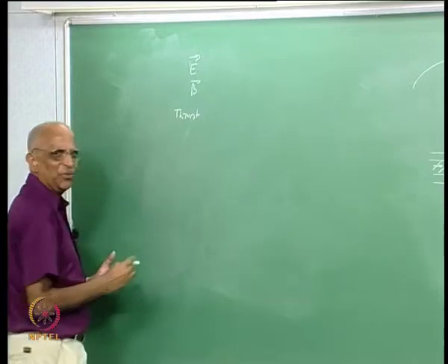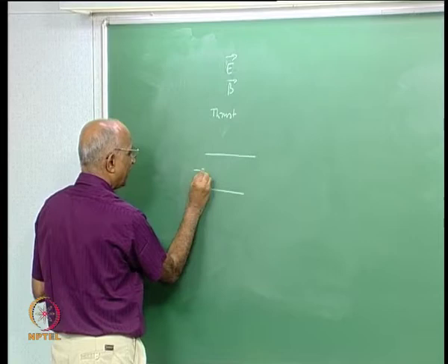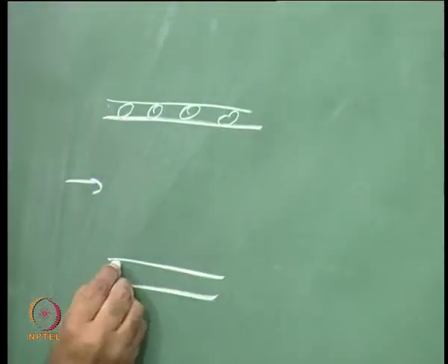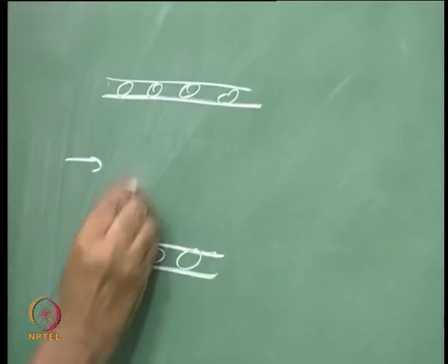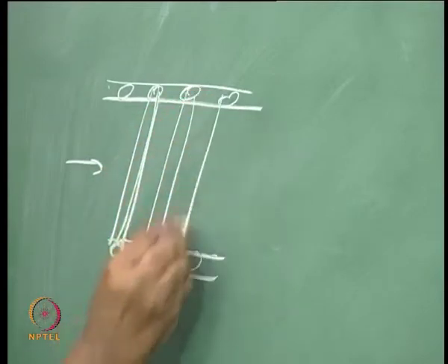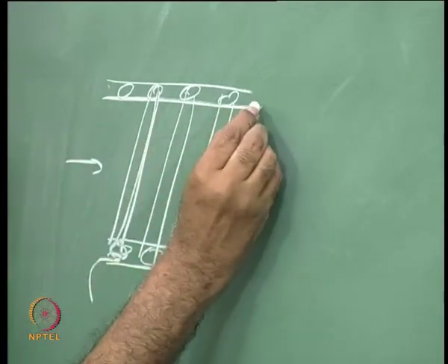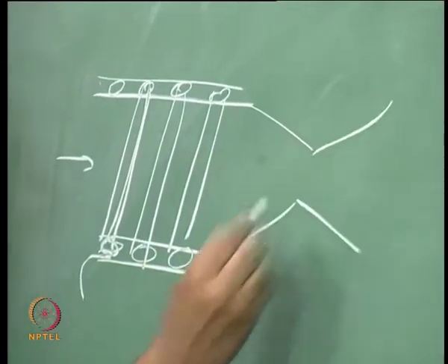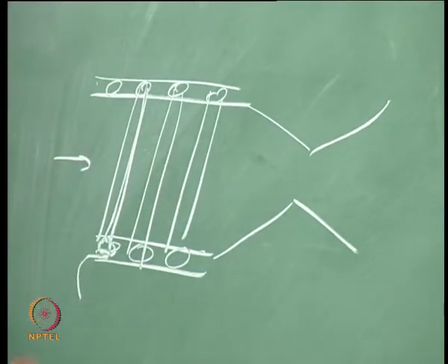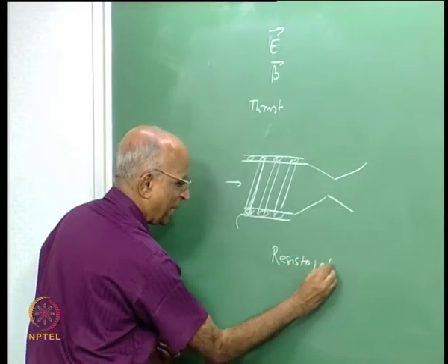But something which was very apparent which we did not do was, supposing I have a gas flow and I use maybe a series of resistances here, I put a resistance coil on the wall, and I pass current through this. Well, I can always heat this chamber, and I could have a regular nozzle. That means I heat the gas using a resistance wire, and these are known as resistojets, but not very practical though.